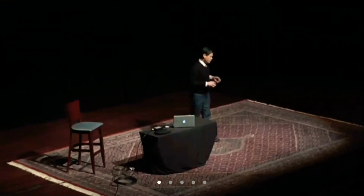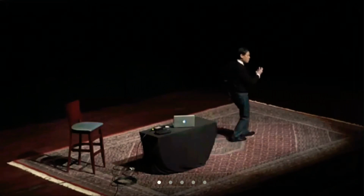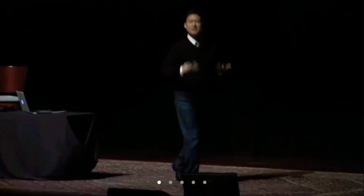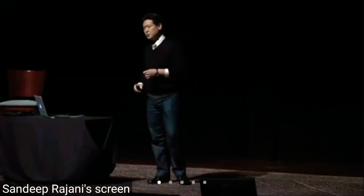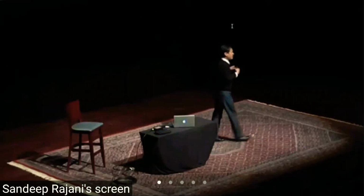But when you look at us human beings, bipedal walking, you're not really using a muscle to lift your leg and walk like a robot, right? What you're doing is you really swing your leg and catch the fall. Stand up again, swing your leg and catch the fall. You're using your built-in dynamics, the physics of your body, just like a pendulum. We call that the concept of passive dynamic locomotion. When you stand up, it's potential energy to kinetic energy, potential energy to kinetic energy. It's a constantly falling process.